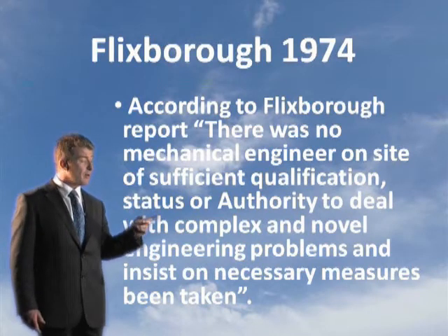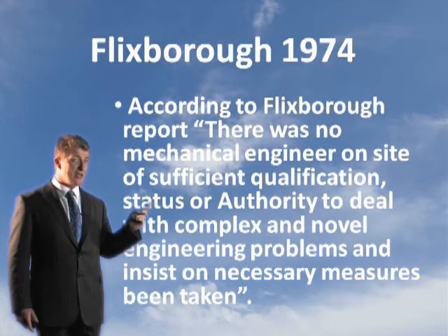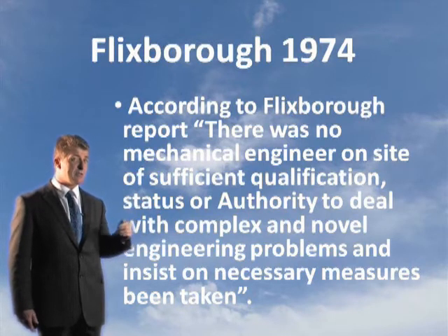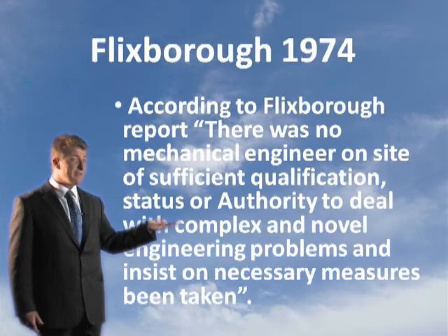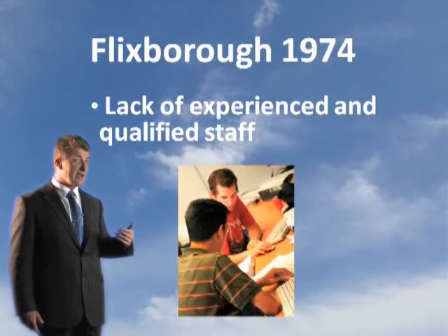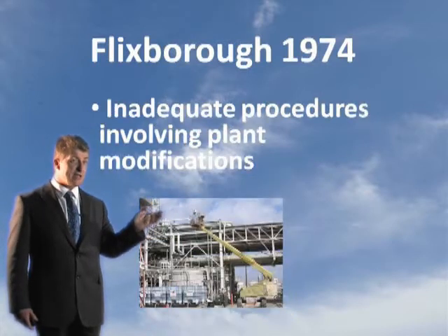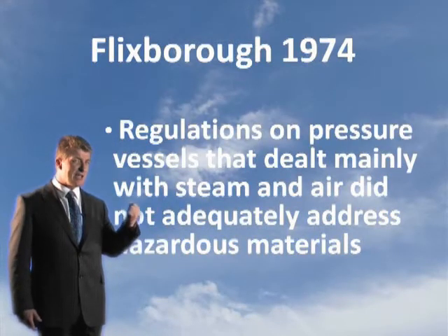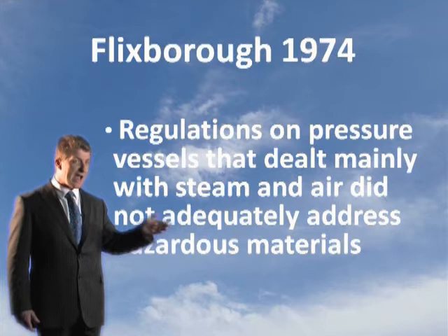The previous works engineer had left and had not been replaced. According to the Flixborough report, there was no mechanical engineer on site of sufficient qualification, status or authority to deal with the complex and novel engineering problems and to insist on necessary measures being taken. Management deficiencies: lack of experienced and qualified staff, inadequate procedures involving plant modifications, and regulations on pressure vessels that dealt mainly with steam and air did not adequately address this.